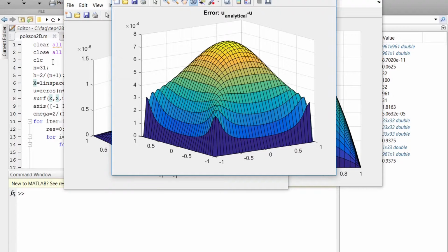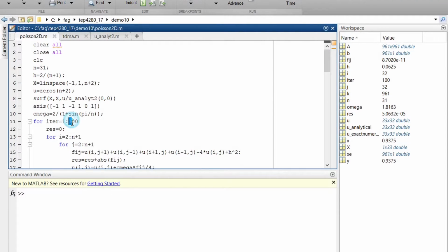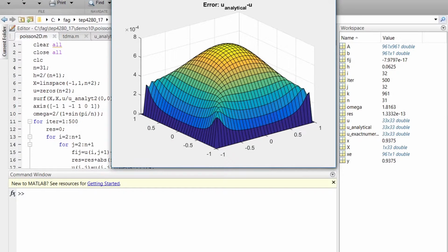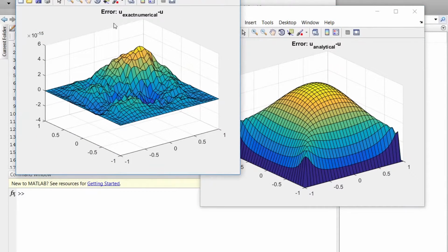But here it really doesn't help if I say increase the number of iterations, 300. Well, we can even take 500. We have time for that. Shouldn't take too long. Just so that you see the residual should go all the way down to the machine accuracy. And yeah, we could have stopped already. And now if we compare, you see this one is now very, very close to 0, 10 to the power minus 50.